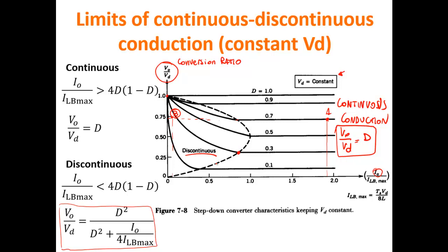So this is why in practice these power management ICs have this DC-DC component, which is the one that one typically considers in investigating the operation of these power electronic circuits. But on the other hand, it has to have a very rapid embedded processor that senses the current and rapidly adjusts the duty cycle controlling the switch. Okay.